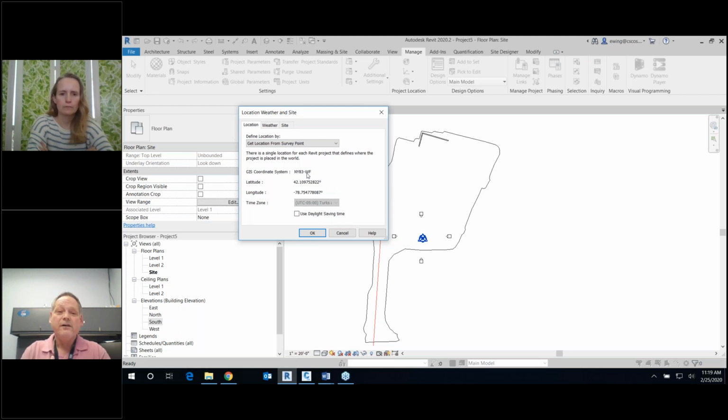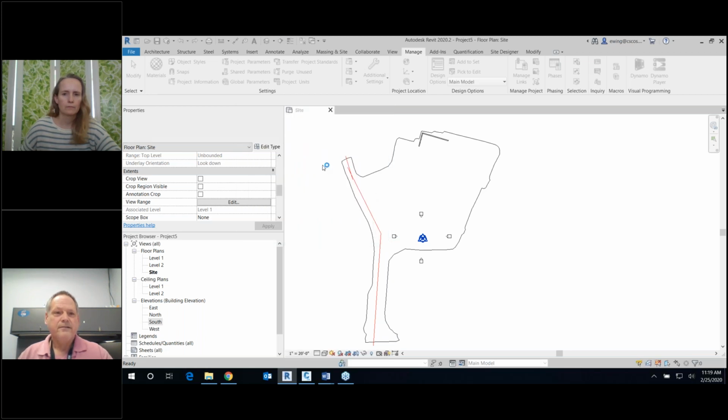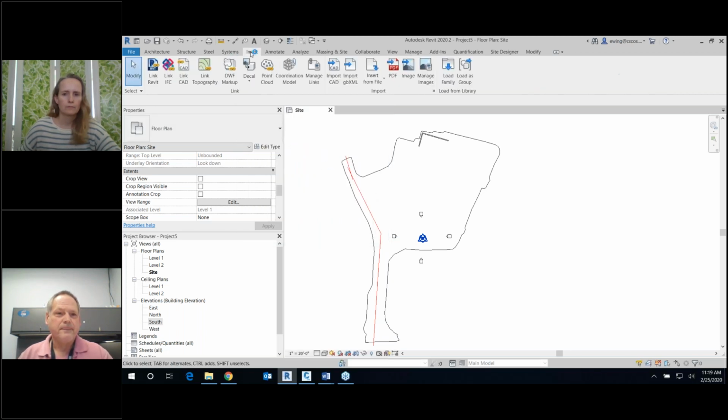So I know that Revit is in the right spot. And the good thing is my project base point, my survey point are right on top of my internal Revit project point. And that's the issue you'll get, right? If your model's 20 miles away from that, you're going to have an issue. So now we know that we're right in the middle of our model, right? So if I hit OK here, now if I want to insert link CAD,